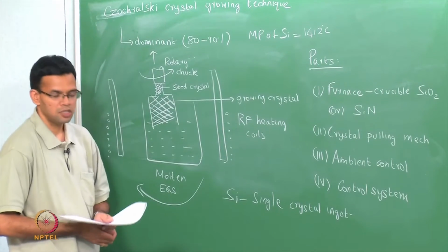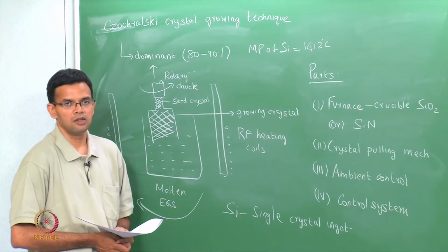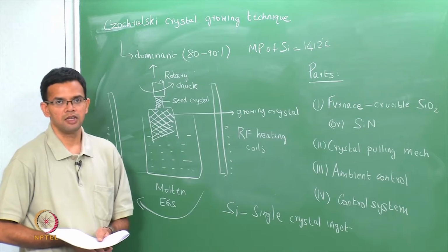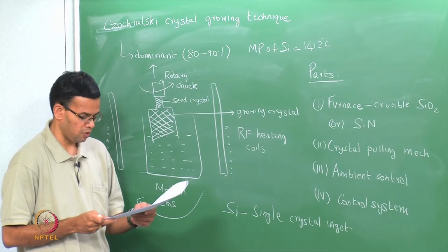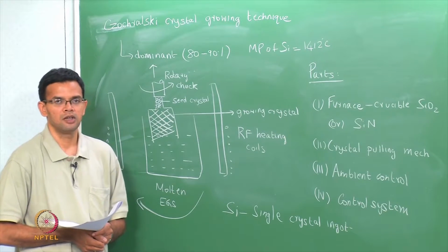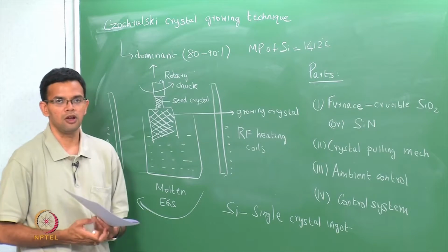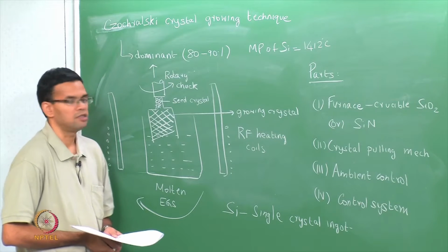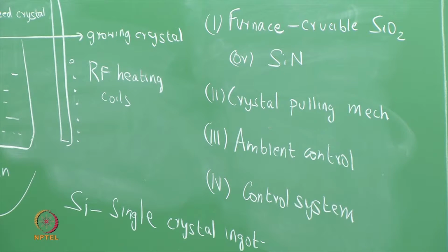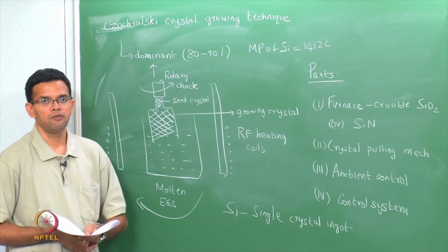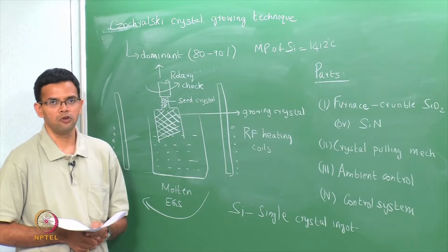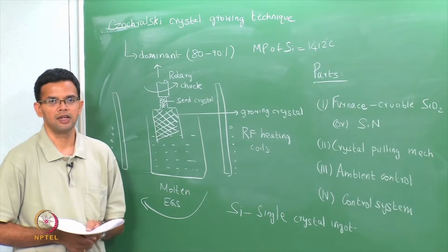If you are doing this for a 450 millimeter wafer, the ingot can get pretty heavy, a few hundred kilograms, approximately 800 kilograms. So, this process is usually automated, so that the entire thing can be done without human intervention. So, one way of growing is the Czochralski growth technique. The other way of producing single crystal silicon wafers is called the float zone technique. Let us look at that next.